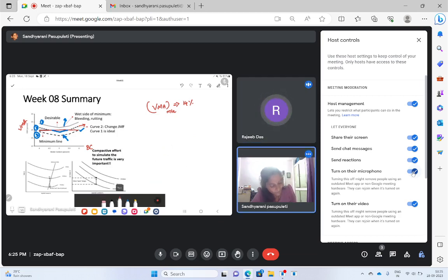This VMA is to accommodate air voids plus bitumen. If I don't maintain this minimum, let us say if I don't say that a minimum of 12% VMA should be there, people can create bituminous mixtures with 10%. Then in the 10%, it may or may not be possible to accommodate the place for bitumen and also air voids.